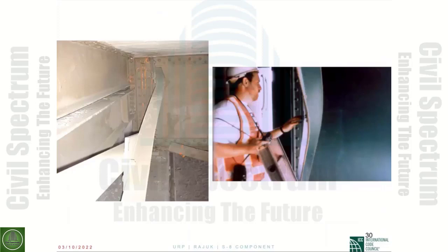We talked very briefly about the steel plate girder bridge. This is here the cross frames between the plate girders. As I told you before, at the location of the support, the cross frames will become primary members for seismic forces, and they need to transfer the seismic forces from the deck, from the plate girders, down to the bearings.